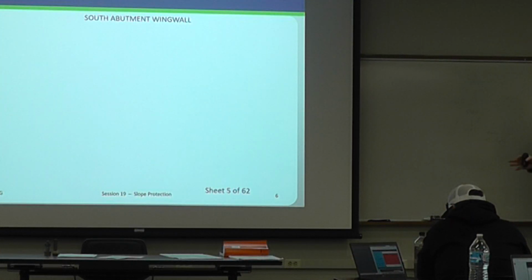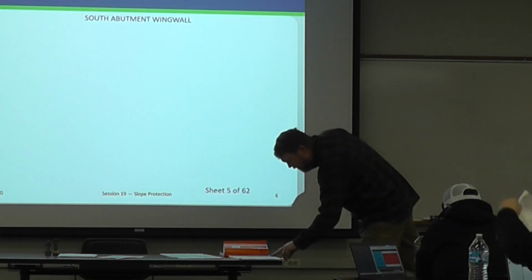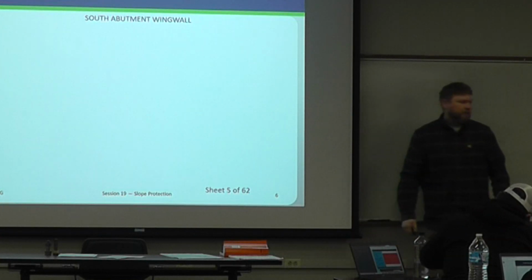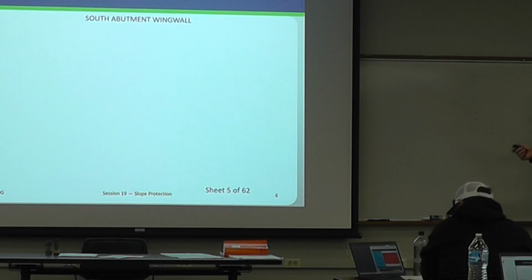So I know you all have the plan set, 27-138 if I remember. Can you pull that plan set out and go into sheets 5, 35 and 60. Just a little plan reading exercise, pretty simple. But essentially we're looking for bottoms of footings and the grade line.